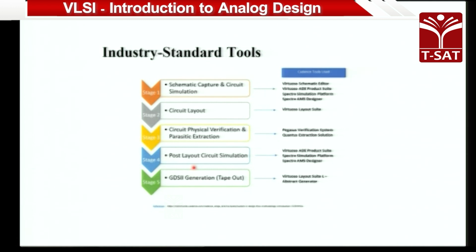And the last thing is GDS2. GDS2 is nothing but a template, a form through which we transfer the design to a silicon fabrication house, right? That okay, take these files, these are 1, 2, 3, 4 files. These files we will send to them, they will take the files into their tool, and those files will be converted into a mask. Mask is nothing but a kind of negative film that we have, right?